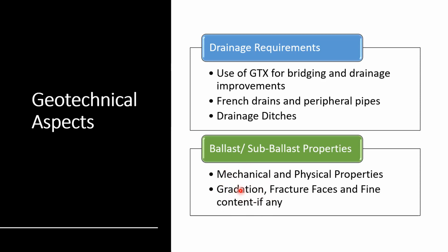For instance, in mining sites, you usually have available quarries, and these quarries are crushed rocks that are ready to be used, and you have to tweak your gradation a little bit to make it reflective of the available quarry that you have on site.